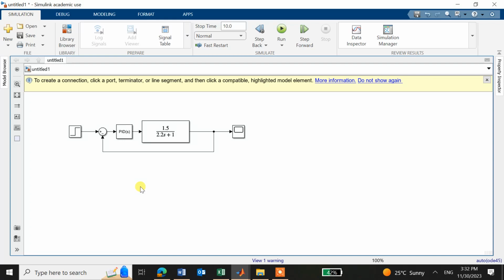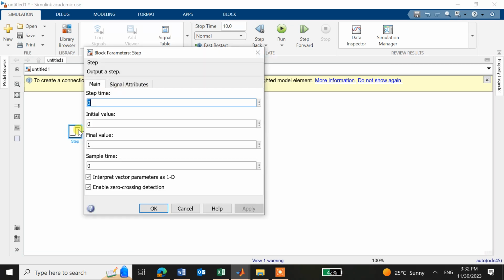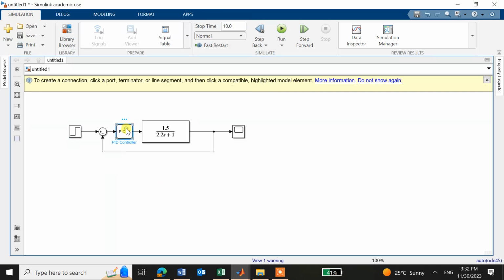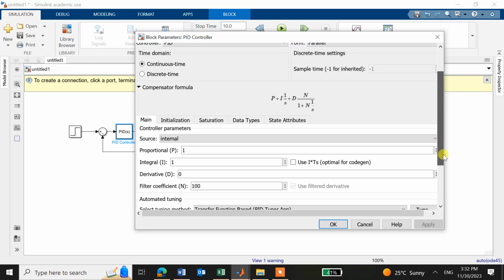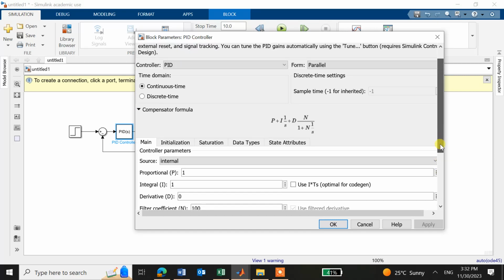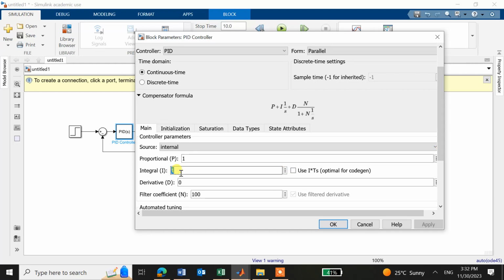Now we will do the cycling. Cycling means what? We will have the set point, a change in set point from 0 to 1, and then a PID controller with only KC. KC, you should have an idea from the process using the root stability criteria, which gives the range of KC. Here I will use some random values. Only a proportional controller we are using.